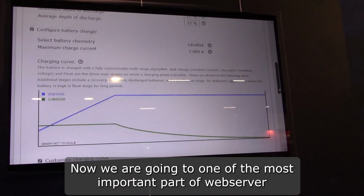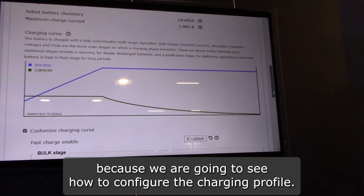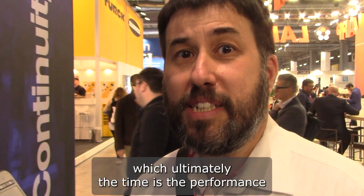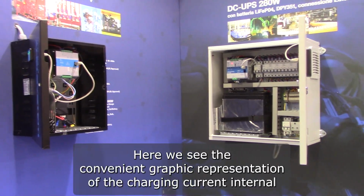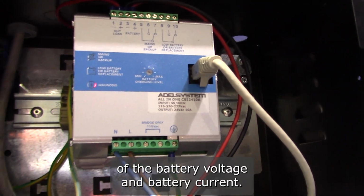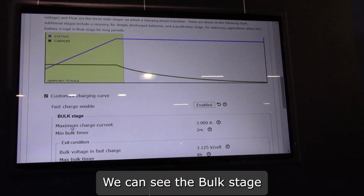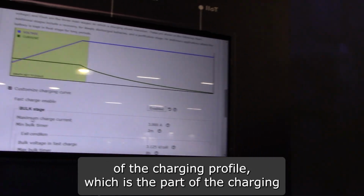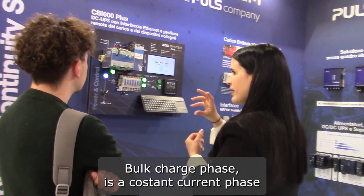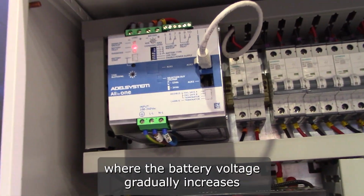Now going to one of the most important parts of the web server, because we are going to see how to configure the charging profile, which ultimately determines the performance of the system. Here we see a convenient graphic representation of the charging curve in terms of battery voltage and battery current. You see the bulk stage of the charging profile, which is the part of the charging which provides the most charge inside the battery. Bulk charge phase is a constant current phase where the battery voltage gradually increases.